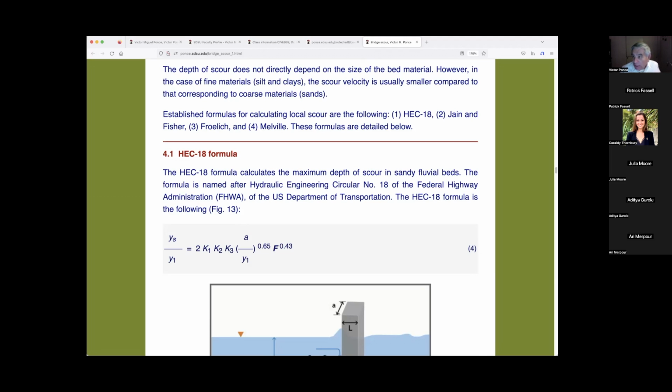There's a correlation, by the way, that can be studied from fluvial geomorphology, between the channel bed slope and the sediment size. A slope of 0.001, or 0.1%, is definitely sandy. And it is also subcritical. In order for it to get to critical, it would have to go to 0.004 or 0.005.